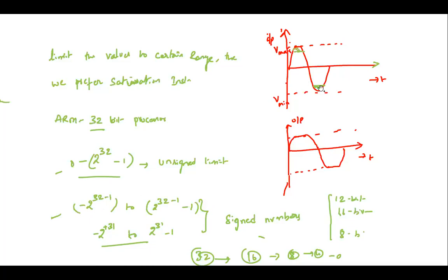Remember, as I told you, once this happens, you can see that this waveform is actually shifted in this format. Which means I am not getting the upper form. This was supposed to be here, like this, and this was supposed to be here, but I'm not getting that; instead that part is chipped off. So that's the use of having these limits, or saturation. I am saturating my waveforms, I am saturating my results, to a certain value. That's the use of these saturation instructions.